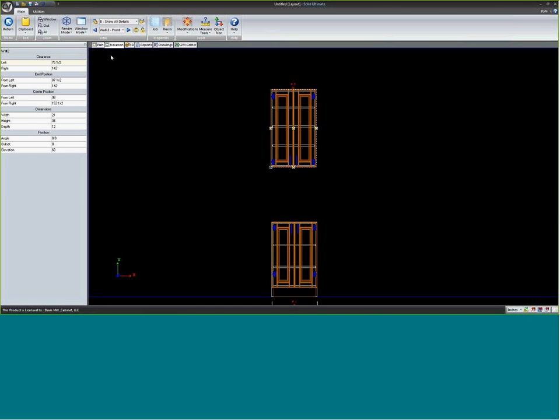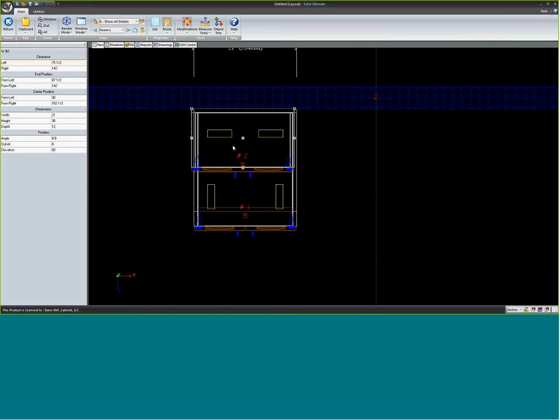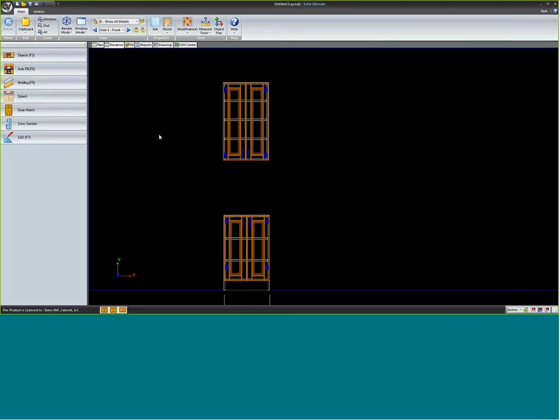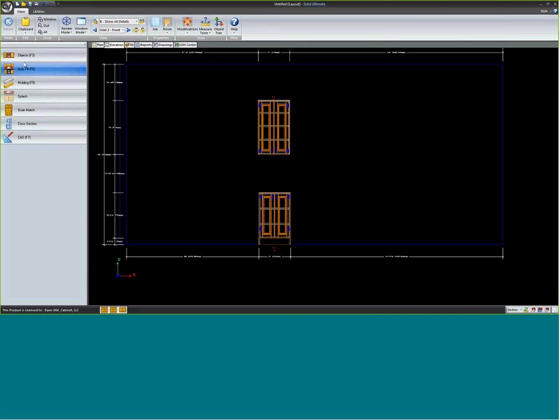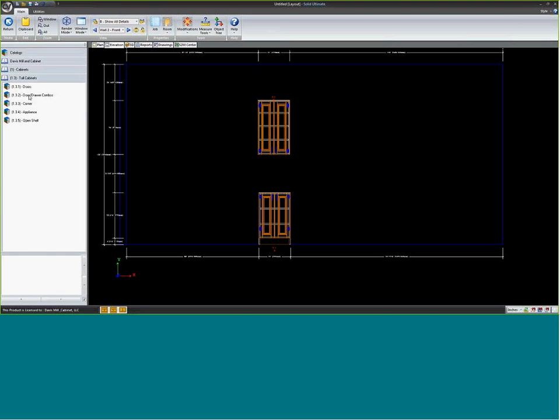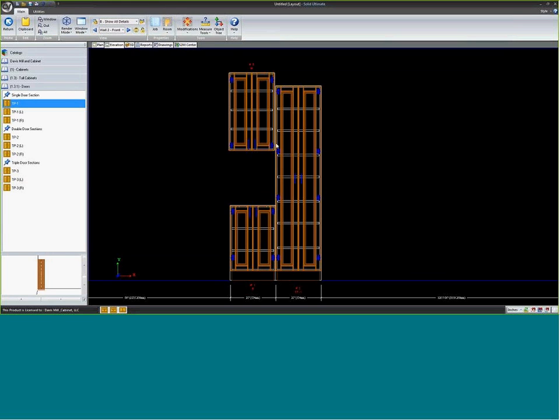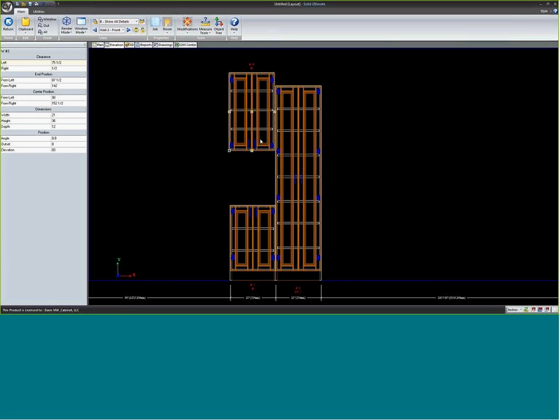So the wall cabinet snaps to that point, even though in plan view it looks like I'm right over the top of it. Obviously, we all know in elevation it's not. Now, a tall cabinet system knows that it can't occupy the same space that either a base or a wall cabinet occupy. So it will butt it to the side of those.